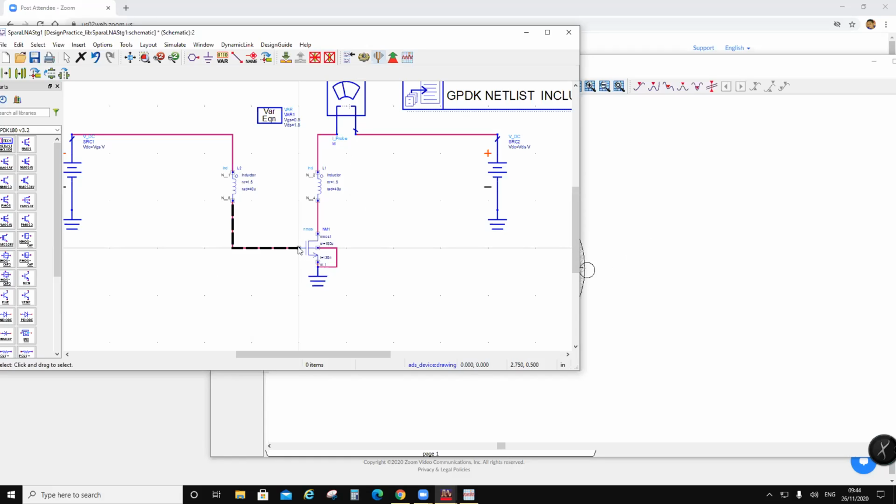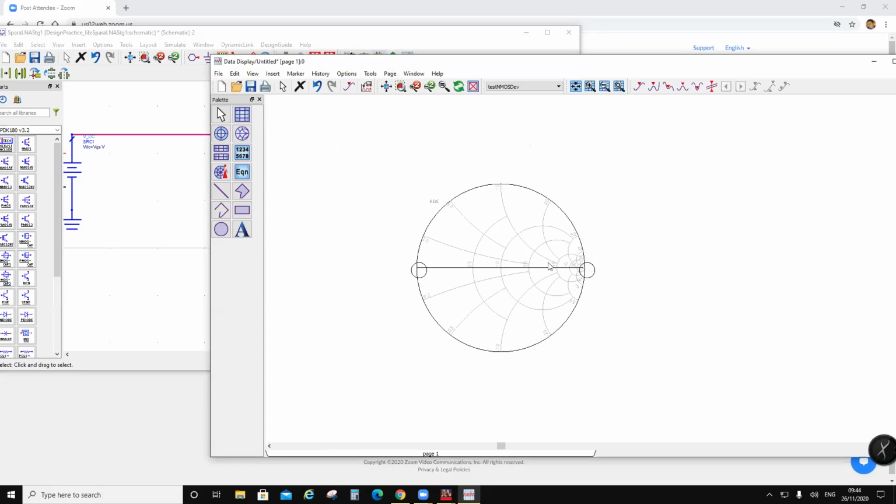So the right way of taking DC characteristics is to show some impedance which is expected to be stable. The one which is stable is farthest away from the periphery, and what is farthest away from the periphery is the center. So if you could terminate this transistor into 50 ohm and then look for the DC characteristics, there are more chances that the transistor will not oscillate. What you will have is a stable transistor, and the transfer and output characteristics will make sense.